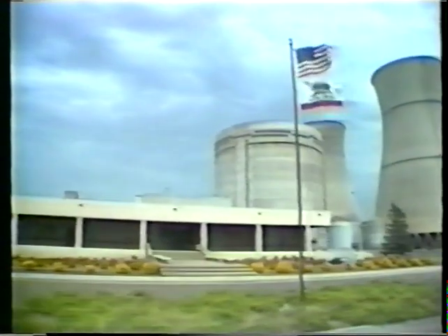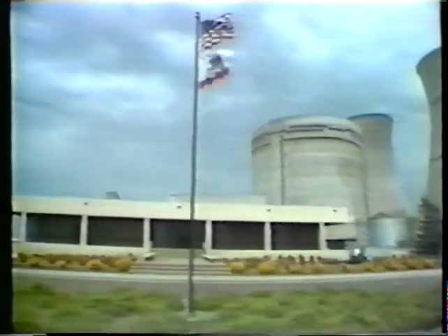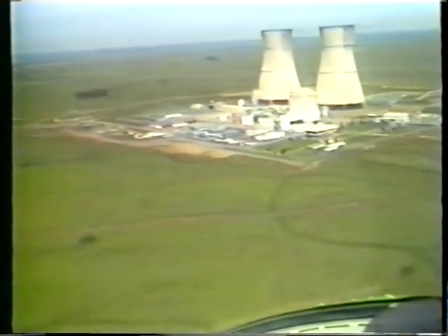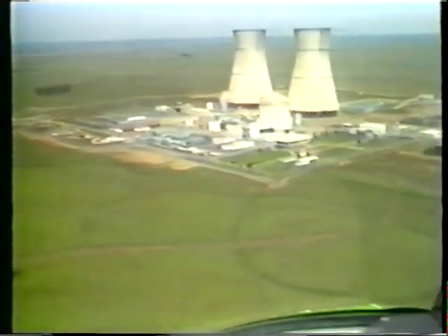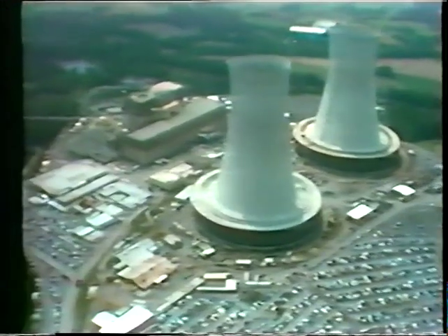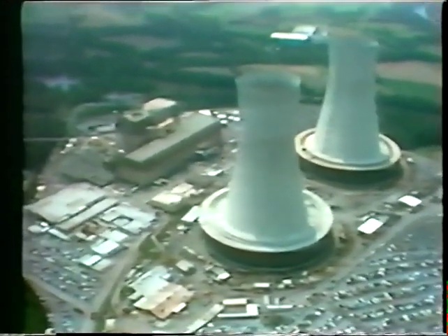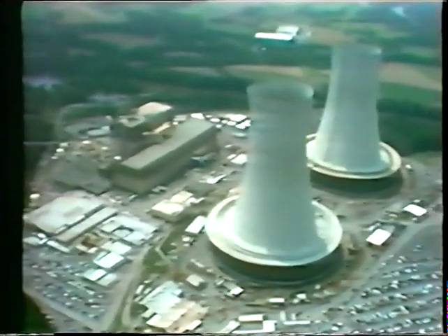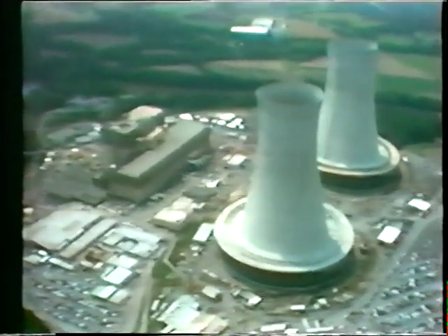The original design for the US nuclear power stations was carried out by the Navy for use in submarines in the 50s. They adopted pure water, known as light water, as their moderator and coolant. To supply the extra neutrons to make up for those absorbed by the hydrogen, the fuel needs to be enriched to 2 to 3% U-235. This takes extra energy and cost.